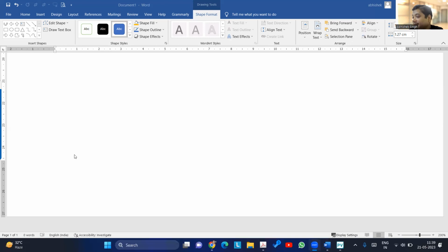Also, for SS material for storage of liquid hydrogen and liquid helium, they are using SS 304, 304L material for -268, -253 liquid hydrogen, but still they are able to qualify -196 degrees centigrade MDMT. I don't know how. -253 is the boiling point of hydrogen. So they are using the same material.